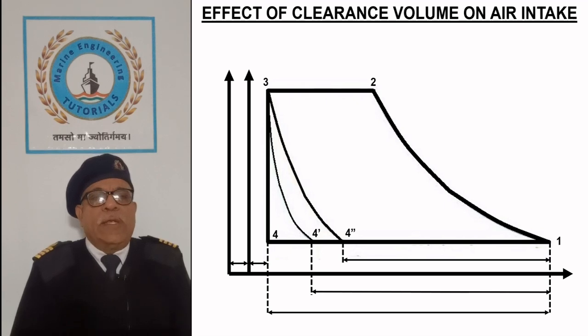Effect of clearance volume on air intake. This diagram describes the effect of clearance volume on intake of air during the compressor's suction stroke. Clearance is necessary to provide the expansion allowance for the piston due to the heat generated by the compression of air.